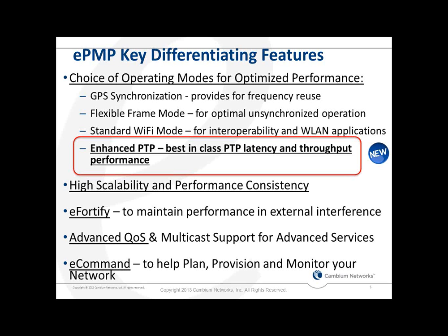We have a GPS synchronized mode of operation, which is most useful for dense point-to-multipoint deployments that allow you to do frequency reuse. We have a flexible frame ratio mode of operation, which has some benefits in both point-to-multipoint and point-to-point deployments, and it's optimal for unsynchronized operation.